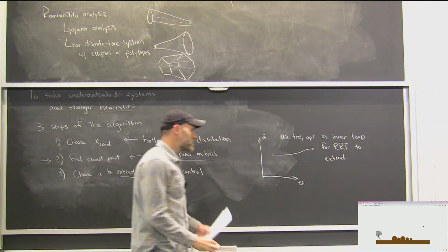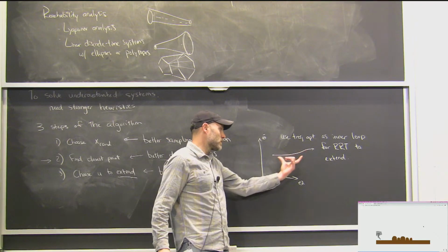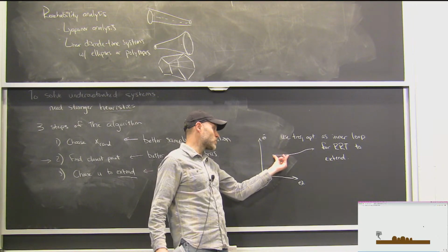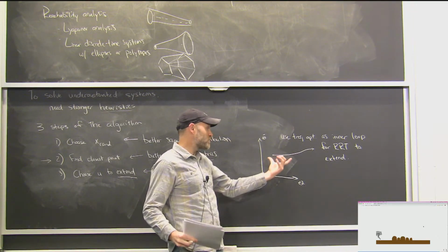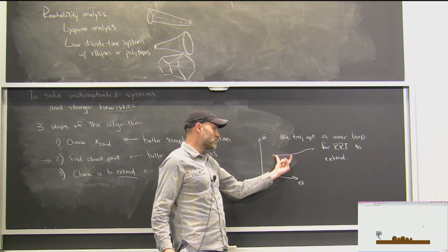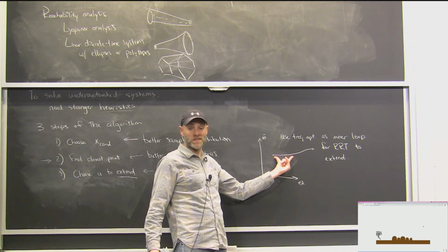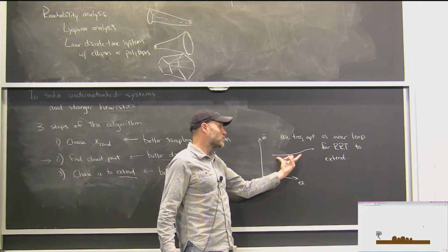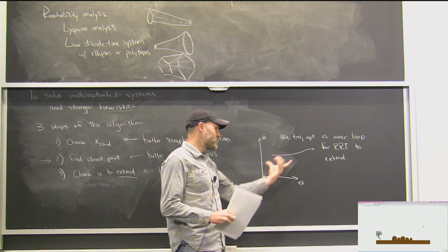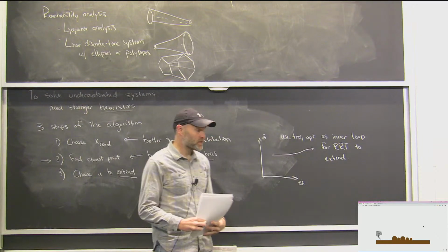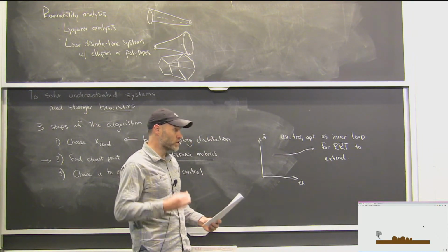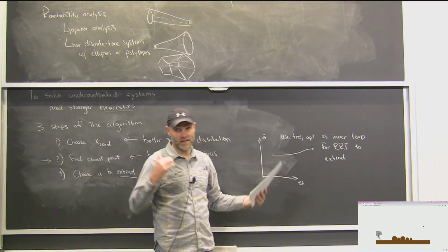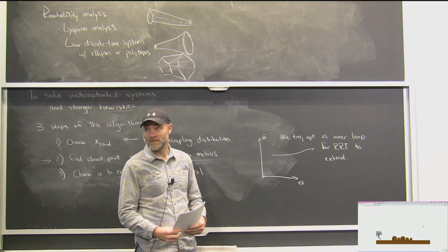And in that case, as long as your trajectory optimization will eventually succeed even when the trajectories are short, if your trajectory optimization isn't super reliable but has some basic properties, like when the problem is simple enough it will eventually succeed, then this can be a very fruitful combination as long as you can make your trajectory optimization fast enough. So a lot of the early work on trying to do dynamic RRTs would use trajectory optimization and realize that that's a pretty slow inner loop, okay?